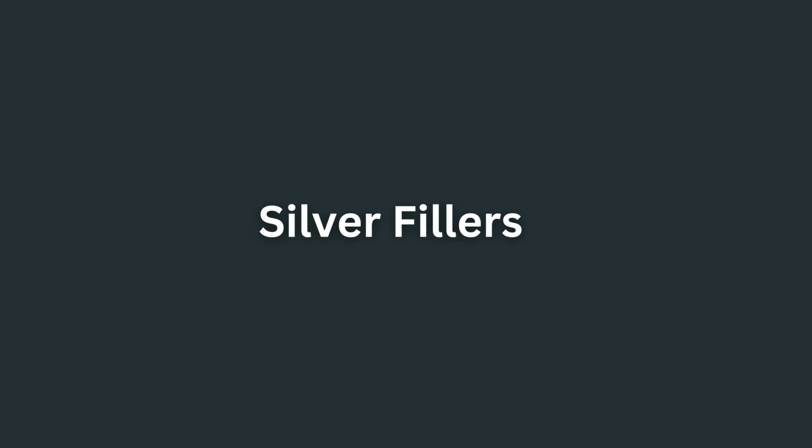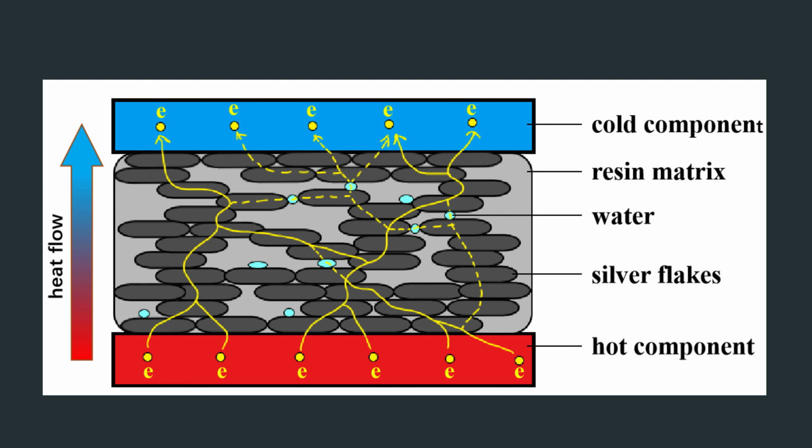Silver fillers. Silver exhibits one of the highest thermal and electrical conductivities among metals and is therefore widely used in conductive adhesives. Micro and nanoscale silver particles can simultaneously enhance both thermal conductivity and mechanical strength of adhesive joints. Silver flakes are particularly effective because their geometry reduces thermal contact resistance between particles.